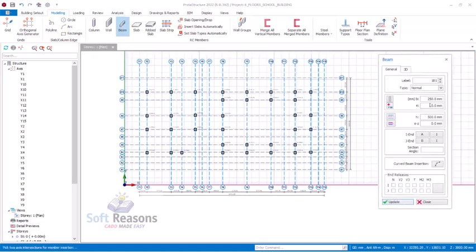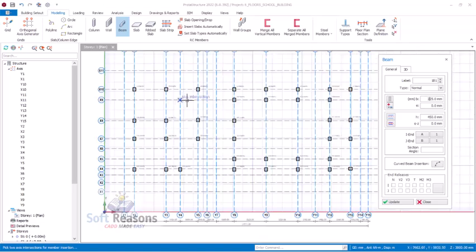In the beam editor, this dialog will be giving the beam width. We have that to be 225 for the beam. We may increase this later, and then we'll have 450 as the beam depth for now. So we are going to be running the beams from that point all the way to this point to have it inserted just like this.